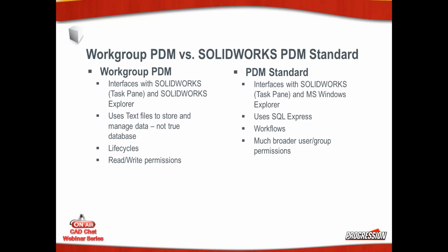As far as Workgroup versus Standard, I thought it important that we try to outline some of the differences. I know that some people may not be using Workgroup and may only be using file folder structures and shared directories on a server. They might be asking themselves, would I want to go with Workgroup PDM or now start using the PDM Standard product? So I thought it important to outline some of the differences. First off, the interfaces are similar, particularly with the SOLIDWORKS plugins and add-ins. There's an available task pane tab that you'll be able to interact with in each product.